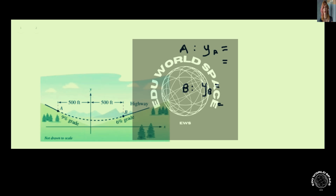So this question is a bit of a long one, so we'll go part by part. The first part asks for the coordinates of points A and B. So we're going to have to find the tangent slope. It shows here on point A that it has a 9% grade, and we can see that they have a line drawn that goes through the origin. So this means we don't have to worry about a y-intercept. And when it says 9% grade, it's essentially giving us the slope, which would be 0.09.